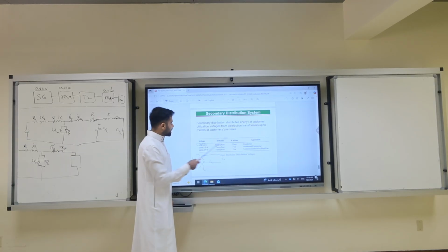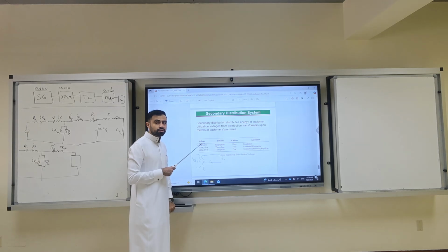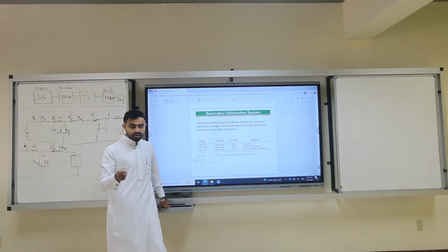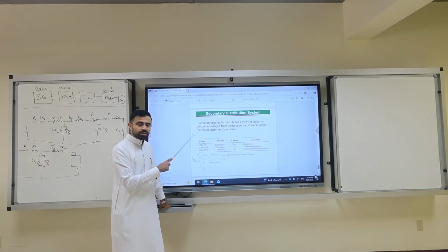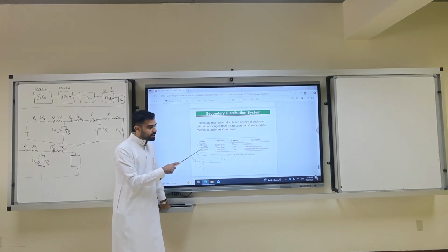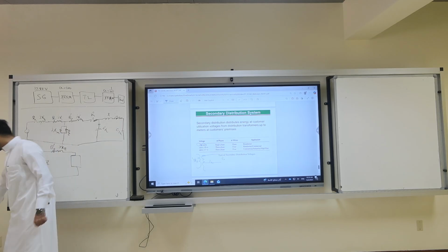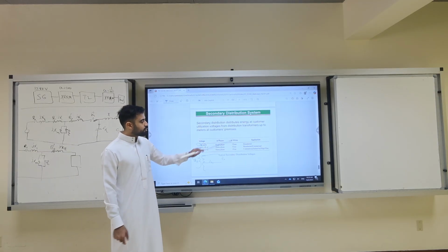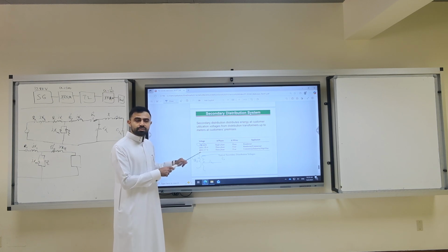So for residential in the kingdom now it has to be around 240, line to line, line to neutral, single phase. For three phase, it has to be 208 Y connected line to line. In the kingdom, we actually increased it now. It has to be 220 for three phase. It depends, 210, 220, but this 120 is not the 120 we have in the old. This is 110. This 110 is line to line. So we have 4 wire, 3 wire. Industrial load, they have higher voltage, 480.